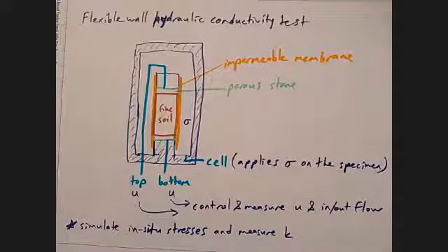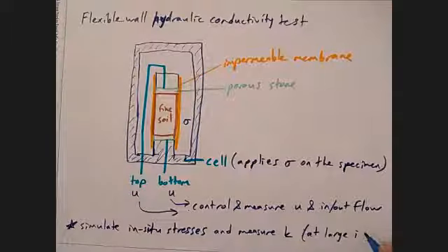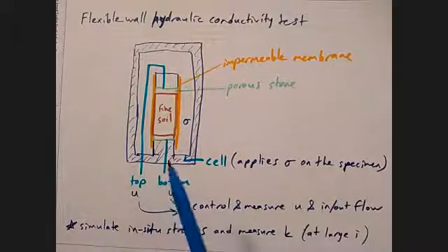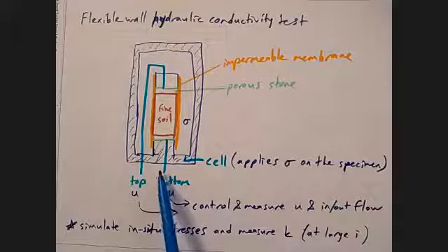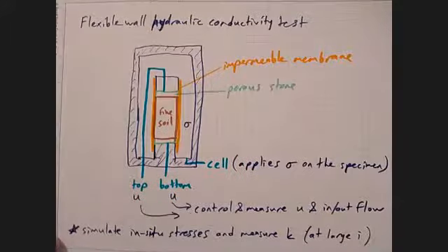Another thing you can achieve is large gradients, because you have a tiny 10 centimeter soil maybe, but you can apply several meters of head difference because you have independent pore pressure control interfaces. So this is the best test you can apply in the laboratory.